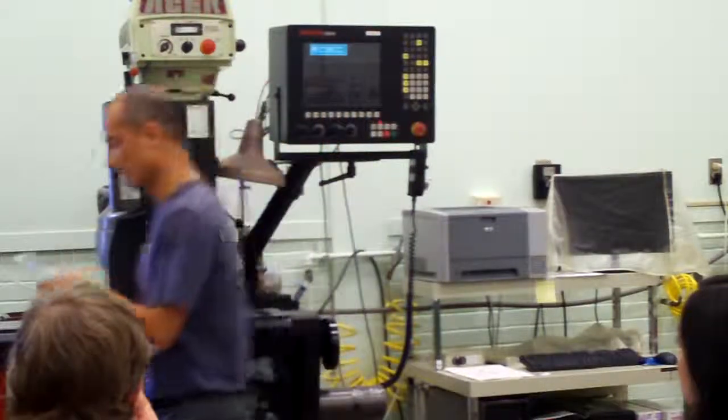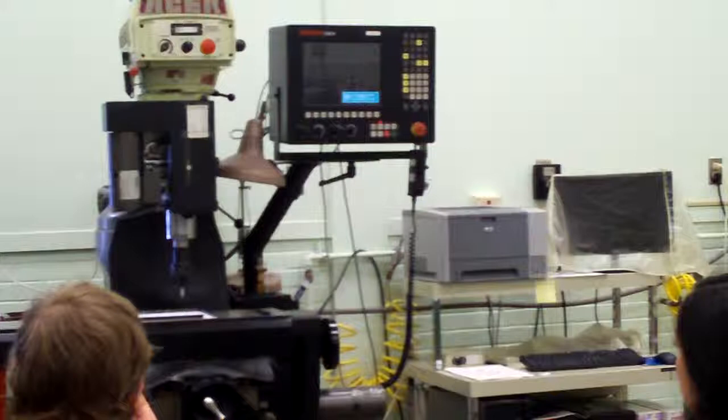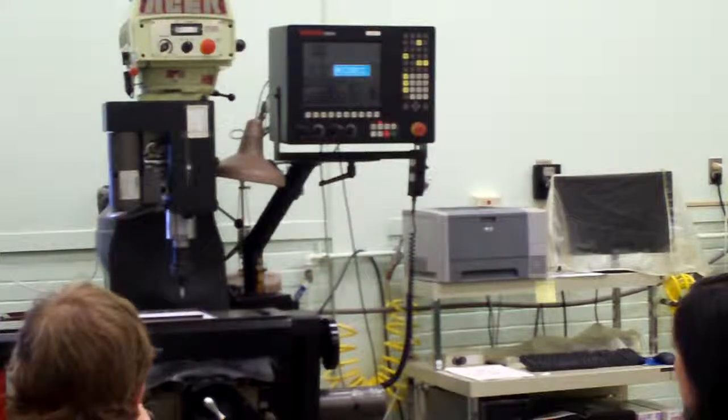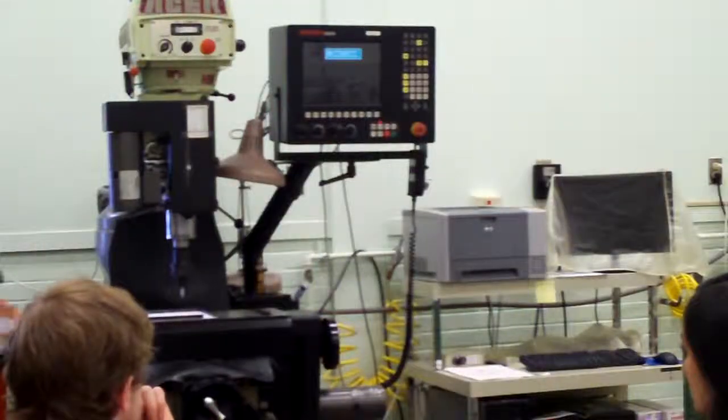The location of the center can be specified using I and J. The IJ is used to specify the location of the center of the circle. The meaning of IJ is: I is the incremental distance from the starting point to the center in the x direction. J is the incremental distance from the starting point to the center in the y direction.